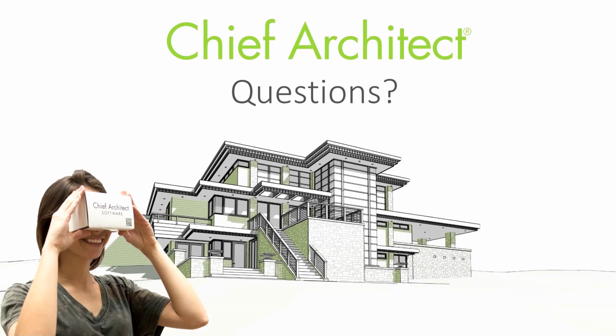Okay. So again, approaching it from turning off some layers or selecting the errant piece of architecture and then focusing on that. Yeah, and sometimes it takes a little bit of trial and error. Sometimes you can't see something because it's behind a wall. I'll even turn on the glass house view and make sure that, can I in fact see it, because maybe I buried it under the floor or behind a wall. And so I'll check that as a secondary as well. Thank you. Yeah.